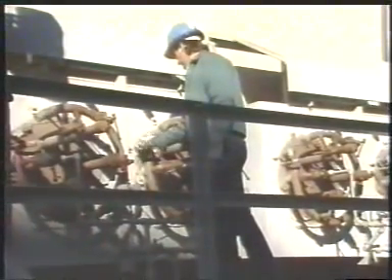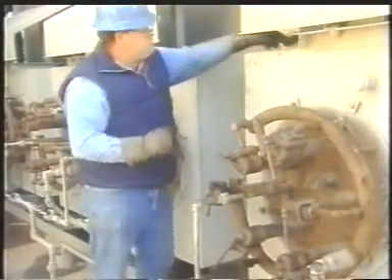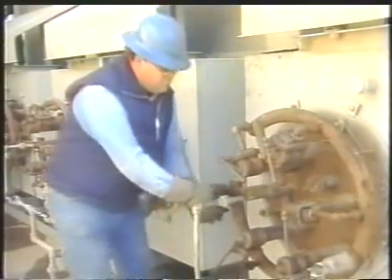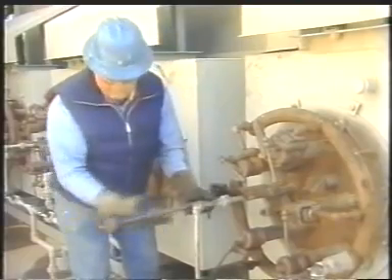Let's start with flame impingement. Flame impingement occurs when the flames are actually touching the metal surfaces inside the furnace, usually the tubes. This contact weakens the metal and can quickly plug up a tube with coke deposits. Flame impingement can sometimes be corrected by adjusting the position of a burner or by pinching back the fuel supply to the problem burner. If these adjustments don't correct the situation, it may be necessary to remove the burner for cleaning or repair.